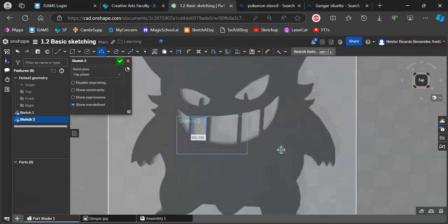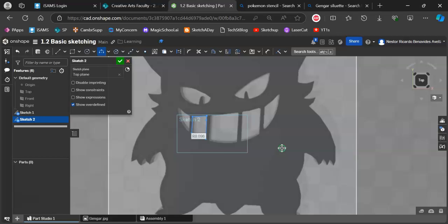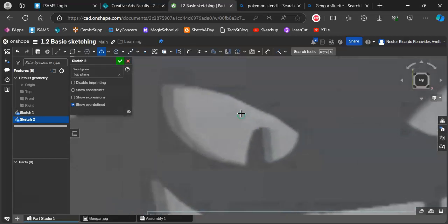Spline will allow us to create the whole shape. Obviously, I'm not going to make the whole shape here in the video, but I want you to see how it's done, right? So for example, I'm going to focus on this eye. I'll select the spline. Just forget about this one. Just go to spline, because it's the easiest one. My advice, try to start in a corner that is a little pointy. So I'll start in the corner that is a little pointy.